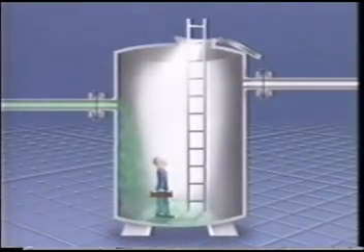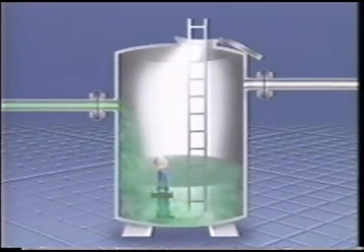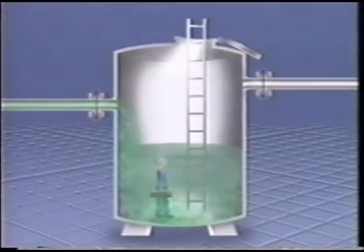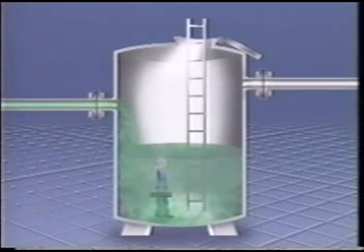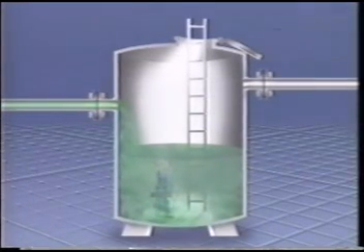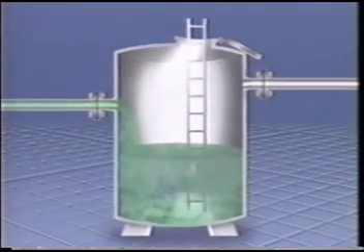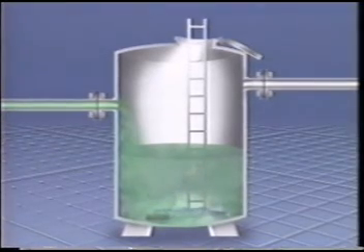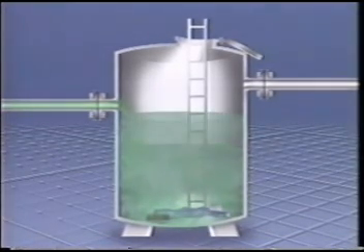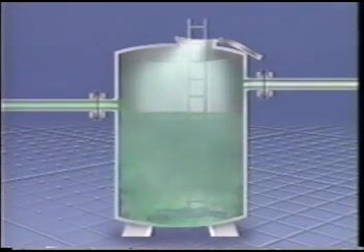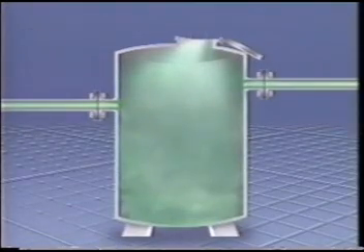Also, keep in mind that carbon dioxide is 1.5 times denser or heavier than air, so it can accumulate in low or confined areas. In a confined space, it will displace the air inside, leaving a potentially deadly trap for anyone who doesn't follow the recommended guidelines for such spaces. Without proper ventilation, carbon dioxide gas will stay in this space for a long time because oxygen cannot displace the heavier carbon dioxide.